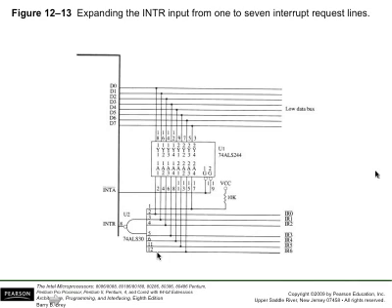So there's no interrupt generated. If any of these devices generates an interrupt, that is to say, if any of these inputs are 0, after this NAND gate, you're going to have a 1. That is to say, any of these devices can generate an interrupt.